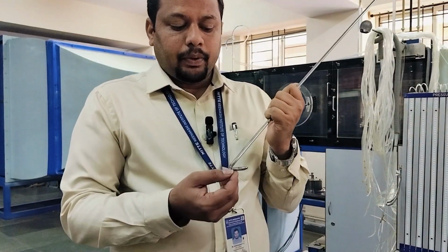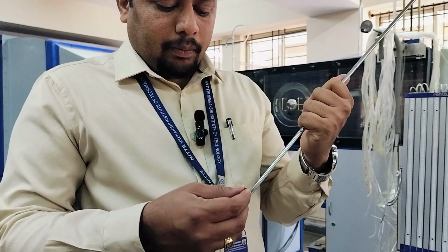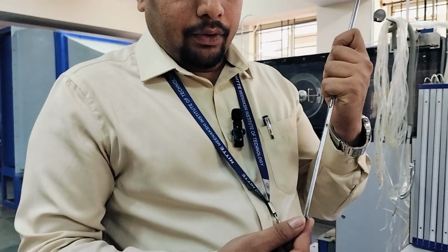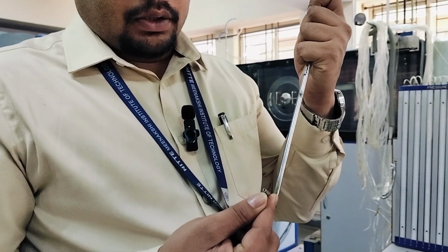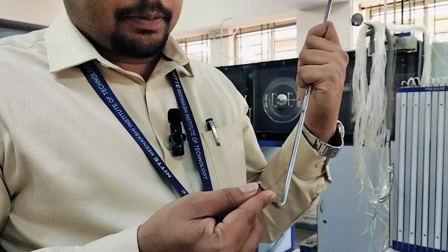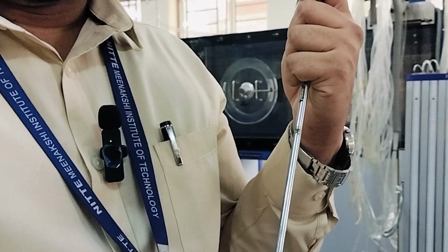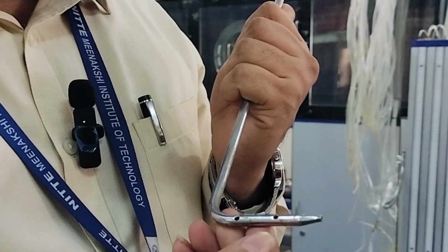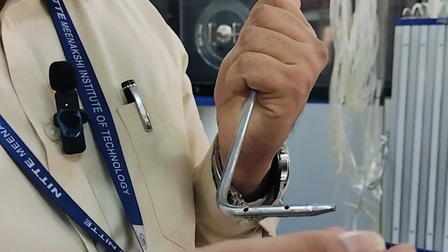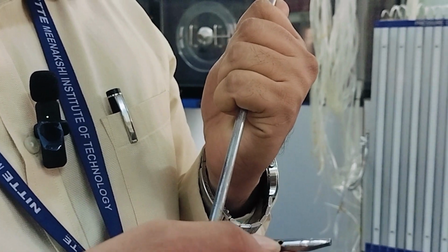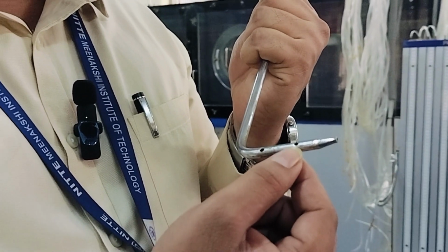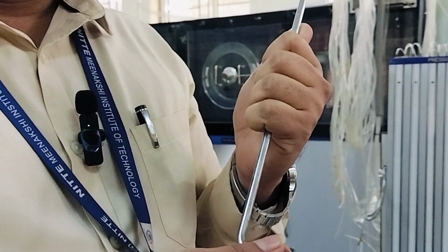So this is a typical Pitot-static probe. The same kind of Pitot-static probe is being fixed inside the tunnel. So here we can see that there is one hole, which is at the mouth of the Pitot-static probe, and at this particular mouth, we can measure the total pressure, and there are two holes which are drilled perpendicular to the flow direction of this particular Pitot-static probe. So here you can see that these two holes will be able to measure the static pressure of the flow.